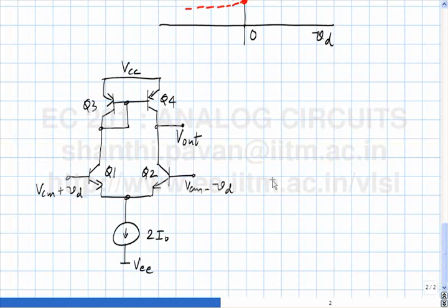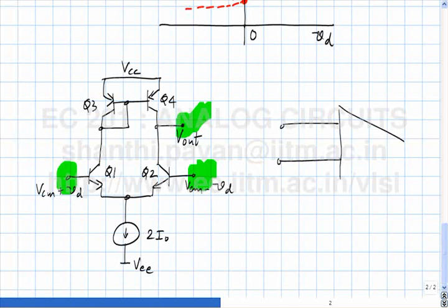This is what the op-amp is basically trying to do. The question now is, are we done, or can I call this an op-amp? It has 3 terminals, 1, 2 and 3. The incremental output here is a large multiple times the difference between these two nodes. So, can I just put this inside a triangle and sell this? Or is there something I'm missing?